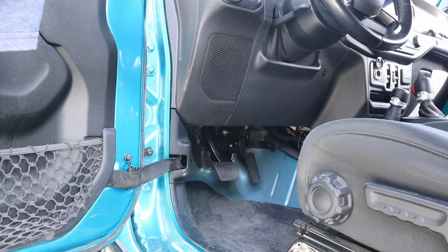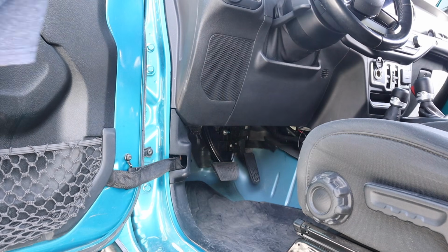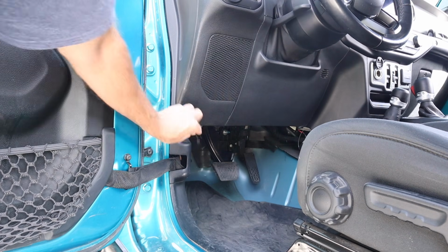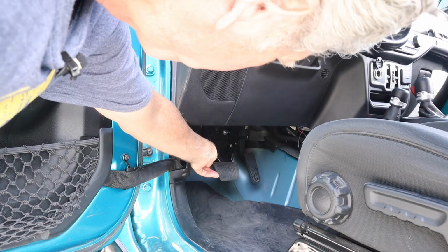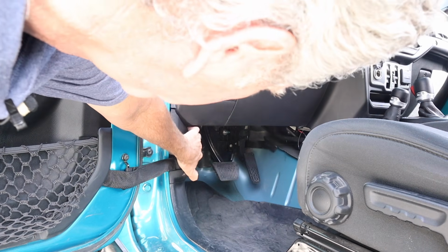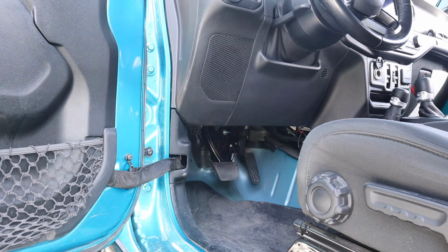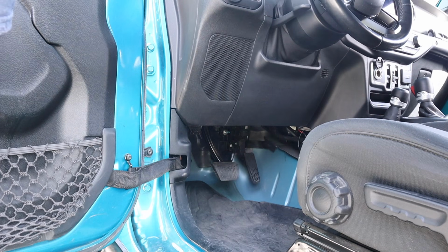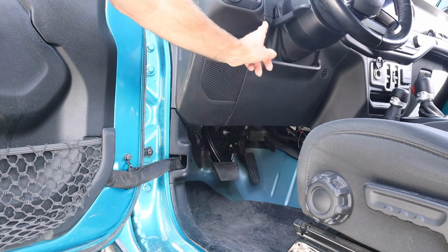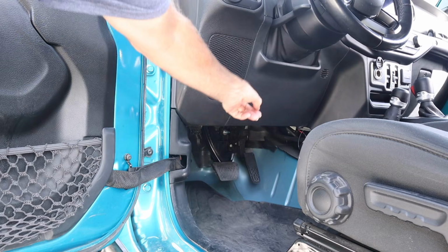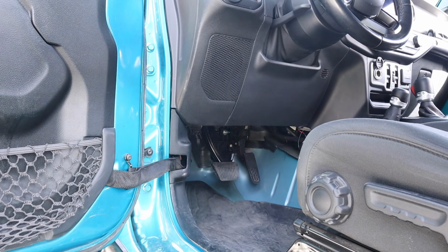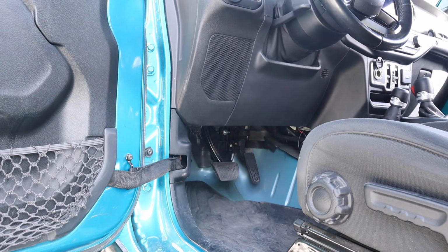All right, the first part of the install is we have to get access to the security gateway cables and unplug them. They're really close to the OBD2 port, which is right here. I found that it's just easier to get access to that port by removing this trim piece right here. If you have a trim panel removal tool, or a spoon will just work, you can use that to remove that panel, and that'll make getting access to those cables a lot easier. So let's do that first.